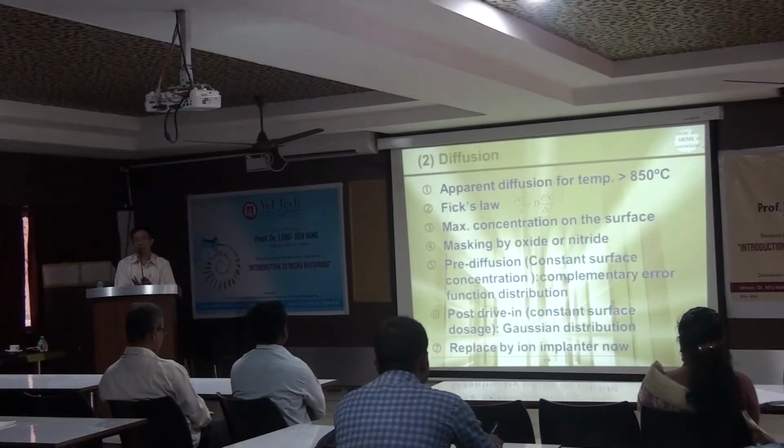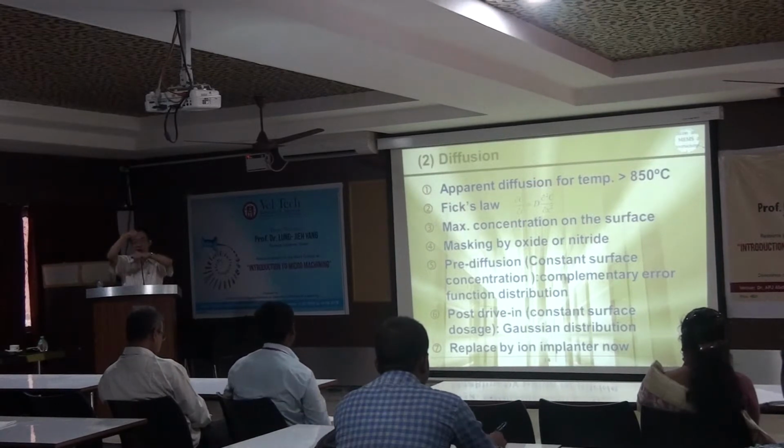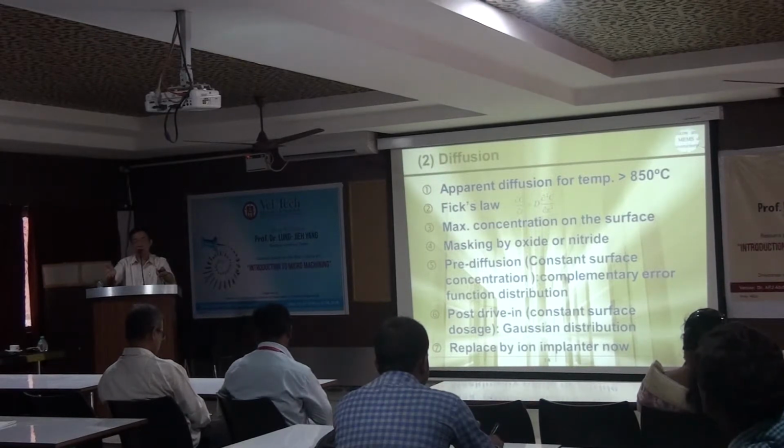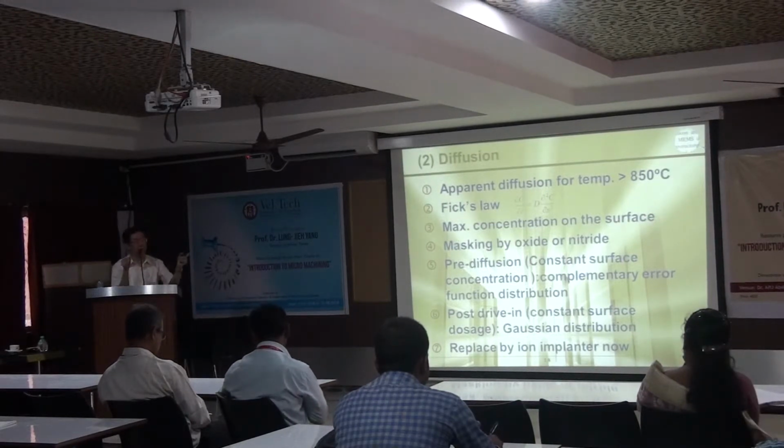Solid diffusion is a diffusion phenomenon that happens in the solid. Dopant is solid, silicon is solid. These two kinds of solid material want to fuse together. Impossible to happen at 25 degrees C, but possible for temperatures larger than 550 degrees C. So it's a high temperature process.